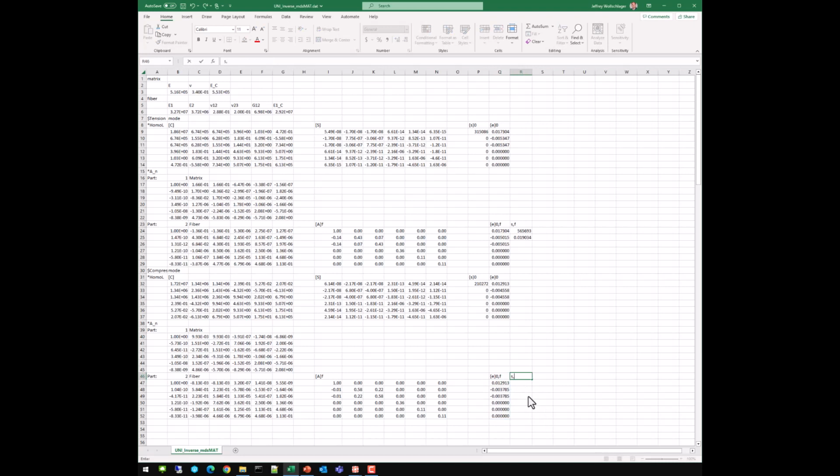I need the stress of my fiber now, which is equal to the compression modulus of the fiber times the strain. So I've got 376 KSI. Yeah, 376 KSI in the fiber and compression. So where I have 565 KSI in the fiber in tension, I got 376 KSI. Okay, and then if I want to figure out the strain at zero stress, it's just 10% beyond that, so about 1.4%.